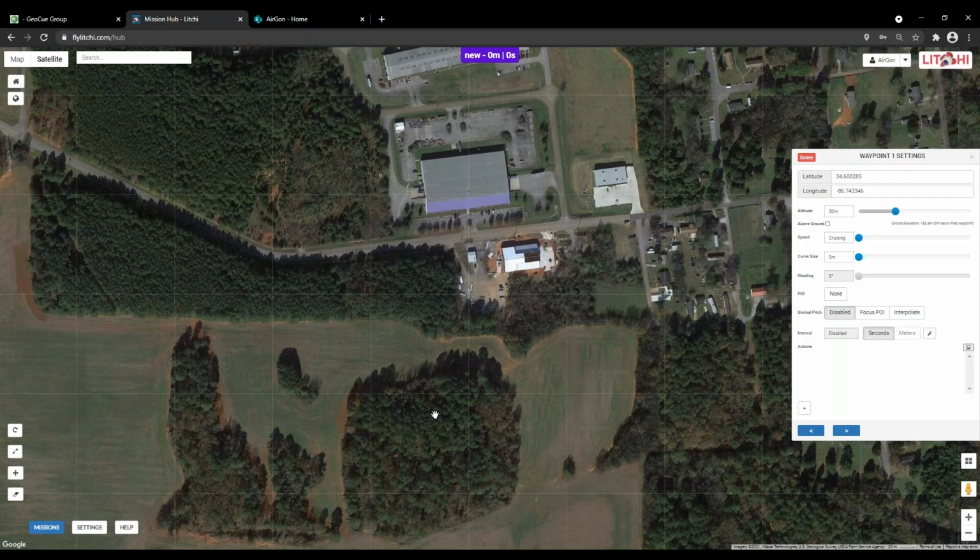So generally for an area collect for LiDAR, we're going to use a predominance of east-west or north-south lines, or on some angle of the lines to cover our area. And then the one thing that we want to do is include what we call cross strip. It's really what it's for is it gives us some risk mitigation for calibration issues or so forth, and we can check the geometric fit of our data and so forth. I'll talk a little bit more about that when I get in here.